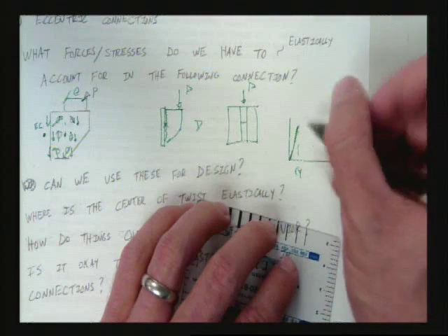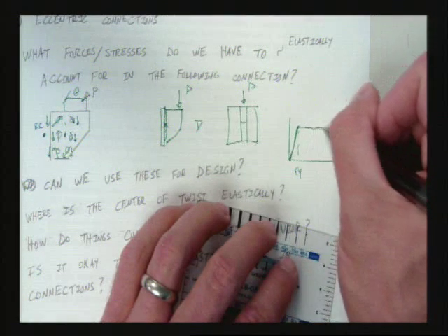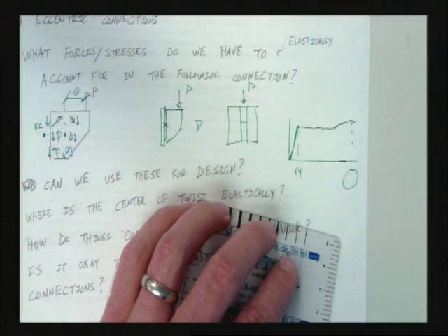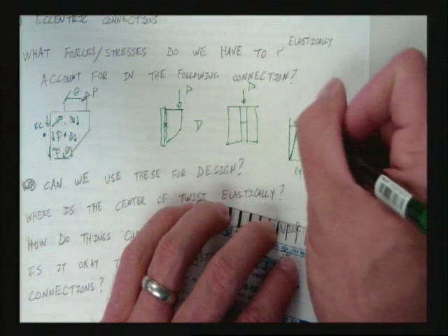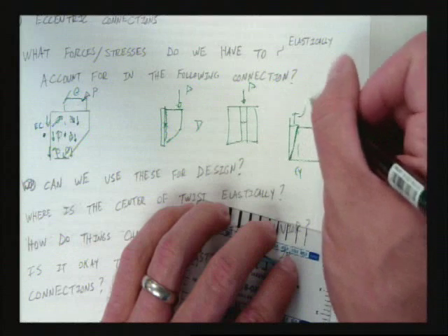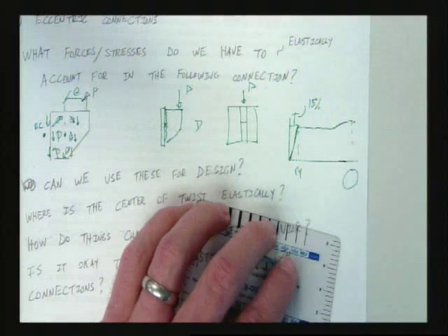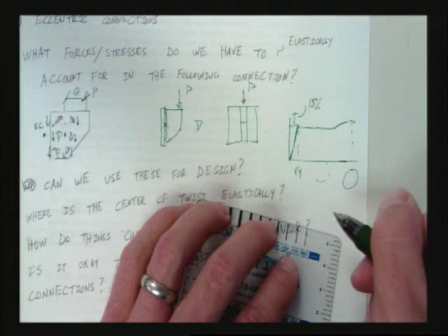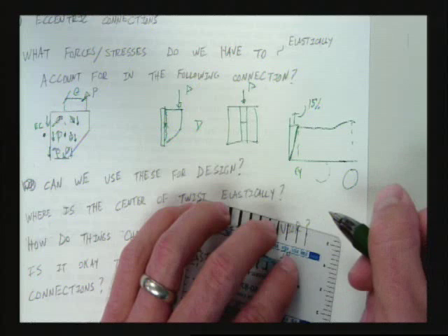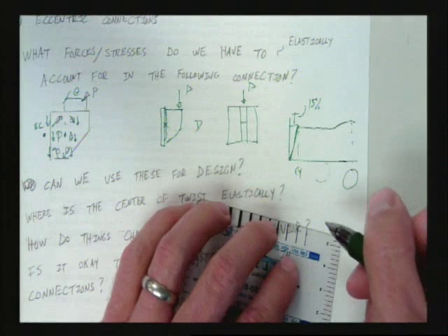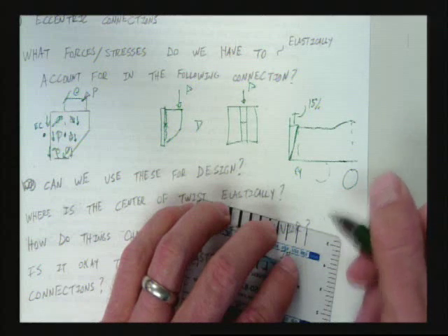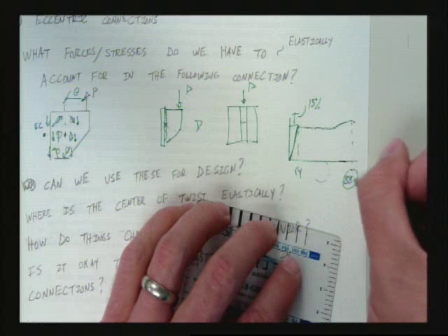What's that? Well, through the yield plateau, then through the strain hardening, and there's this point. And how much further is this point than epsilon y? 15% is here. That's right, though. Good answer. 15% increase in strength. What is the increase in strain? 88 times. This is 88 epsilon y.